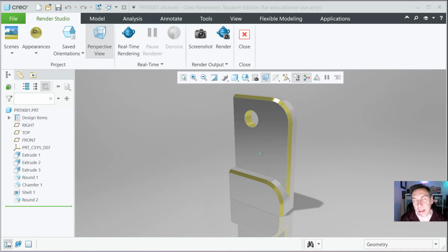Now, in this release, what we're going to build is what you see on the screen right here. It's essentially the very foundations of modeling. We're going to draw some sketches, extrude them into the third dimension, and also remove material that way. We're going to put on some fillets, that's what you see here, or what they call rounds, the radiuses.